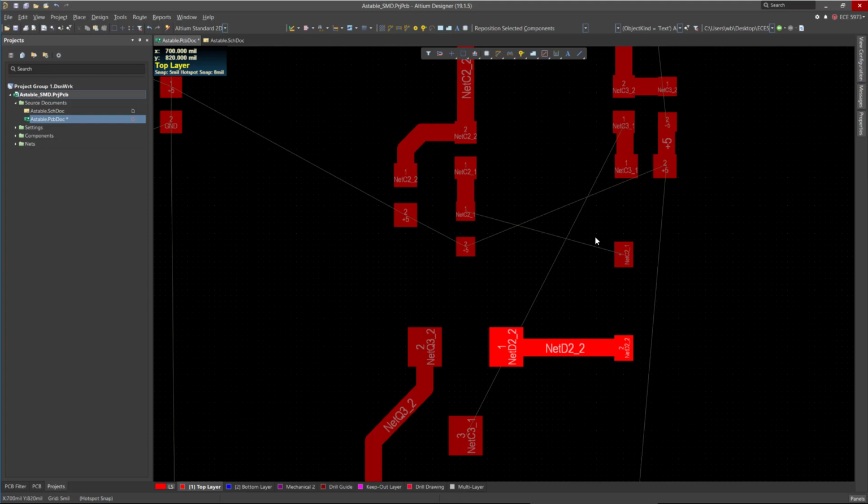So if you have a data bus with 8 bits, you need to route all these 8 traces together from point A to point B, and they have the highest priority. So if you have high-speed signals, they have the highest priority. Don't give priority to low-speed or power supply signals to change the layer for these traces from layer to layer to allow other low-speed signals to pass.